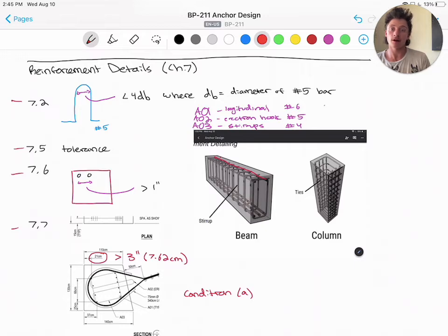A02 or number 5 bars are used as erection hooks and are analyzed separately in the constructability checks. A03 or number 4 bars compose the stirrups. These provide shear reinforcement for the beam as well as hold the longitudinal bars in place during construction.